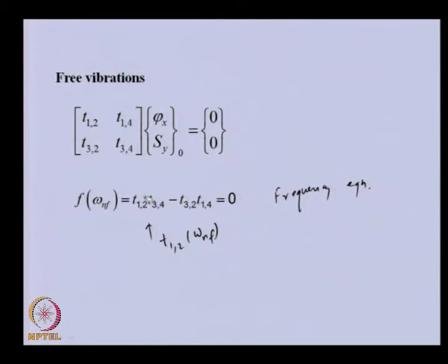For the transverse vibration case, this polynomial will generally be of higher degree, because if you are dealing with a larger mass rotor system, then obtaining this polynomial will not be easy. So, generally we solve this frequency equation using numerical analysis techniques. We explained that in the torsional vibration case also. Some kind of root searching technique can be used to obtain the roots of this frequency equation.